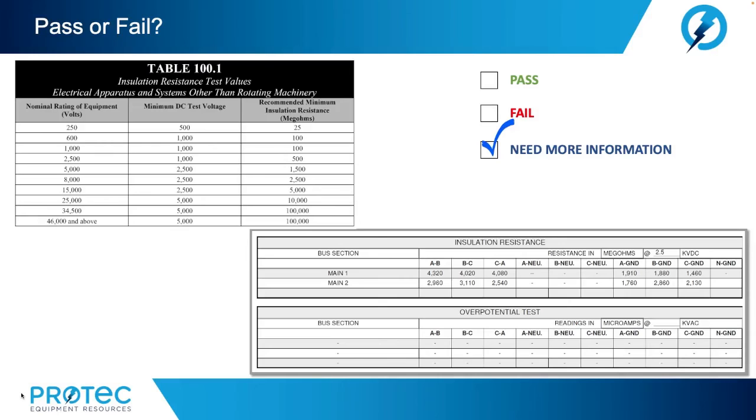Okay? Now, if we are testing the bus bars that are inside the switchgear cabinets, the verbiage in the NETA ATS and MTS procedures under distribution switchgear does not necessarily address or specify the correction factor. But if we are testing the bus bars inside, we can refer to the recommendations for testing busway.